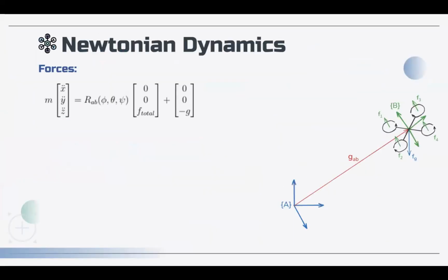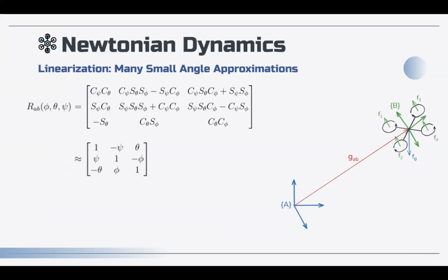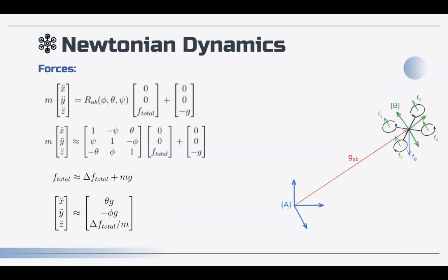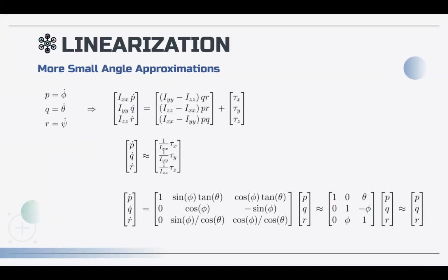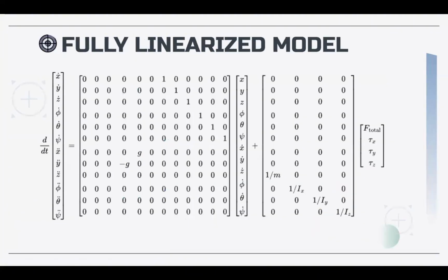Afterwards, we decided to compare this method's performance against an MPC controller that used a constrained LQR optimization. To build a dynamics model for the optimization constraints, we first linearized the translational Newtonian dynamics of a quadrotor in stable flight, using the small angle approximation to obtain a linear state space representation. Using the same method, we also obtained the quadrotor's angular dynamics in linear state space form, which gave us the collective linear state space model for our optimization.